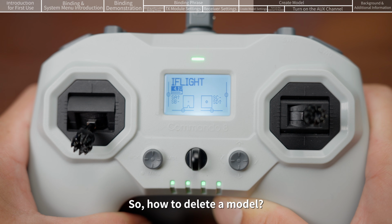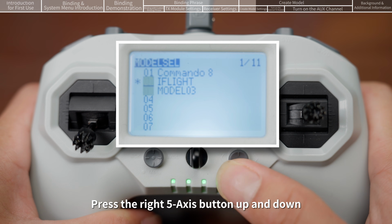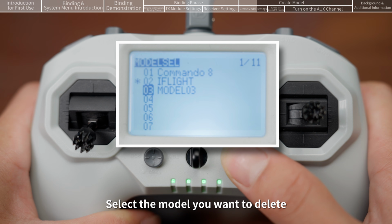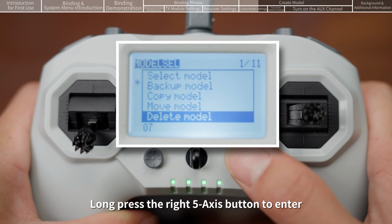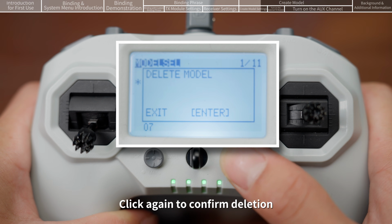So, how to delete a model? Press the left 5-axis button to the right to enter the model menu. Press the right 5-axis button up and down. Select the model you want to delete. Long press the right 5-axis button to enter. Scroll down and select Delete Model. Click Delete. Click again to confirm deletion.